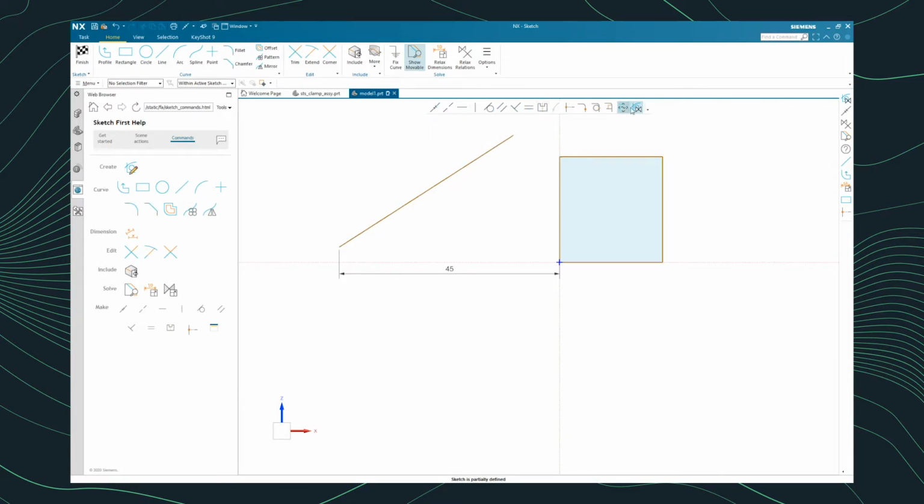And you can see this is our Sketch relations toolbar, or scene bar is what it's referred to as in the new software. But with this new user interface and new Sketch solver, the relations have changed a little bit. As you can see, the make coincident operation here on the end, the very first option. If you look at the description, it does say move selected objects to become coincident, concentric, or point on curve to the last selected object. So they took basically three different types of relations and consolidated those into the make coincident functionality here.